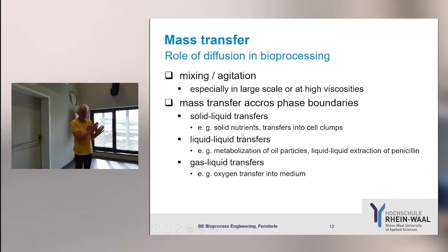So that's kind of diffusion at a plane. But if you wanted to make it happen faster, would you use convection? You need to remove the phase border. That's the point. So if you have your window open, but you have here a membrane where your water can diffuse through, but the wind cannot get in, you have to wait a long time. And even if the air in your room is completely mixed, and outside you have wind like hell, so it's transported away immediately, but still you will have to wait quite long. That's the comparable situation with the phase border. And of course, this is something you would not like to have there.